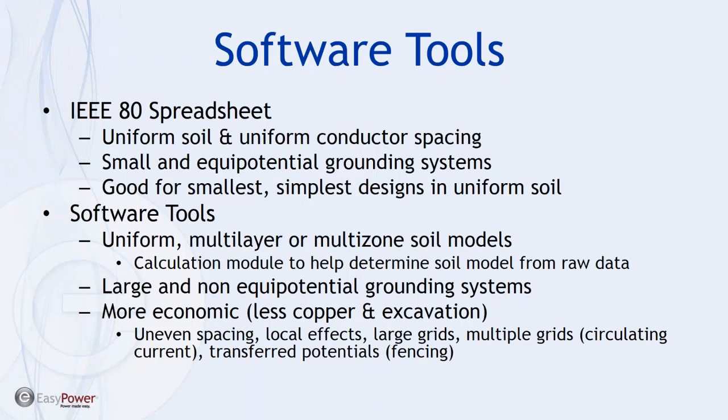Transfer potentials being those where maybe you have a fence running adjacent to your site and you want to know whether or not you want to ground that in a certain way or connect it to your site. And so you can model that, and you'll see the potentials developed around the fence and on the fence as a result of that, and determine if that's also safe for step and touch during your fault condition.